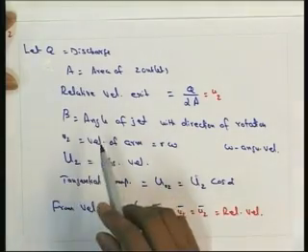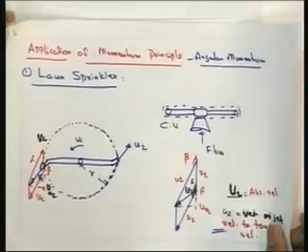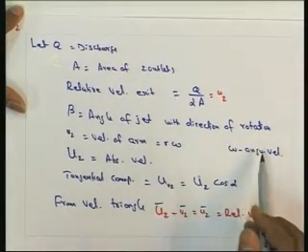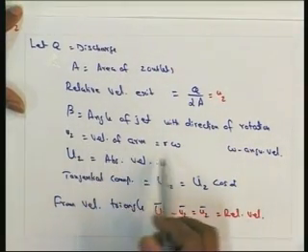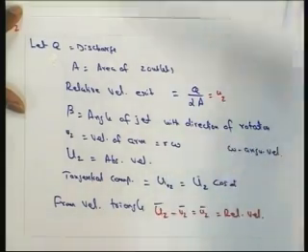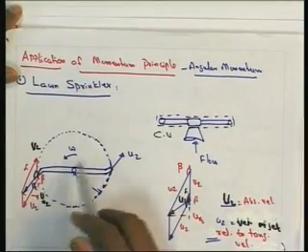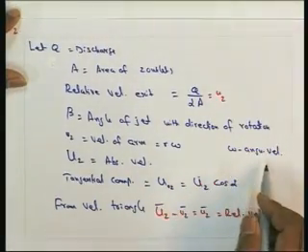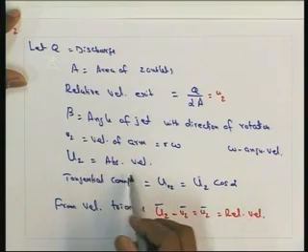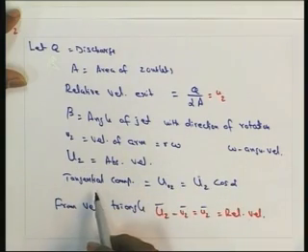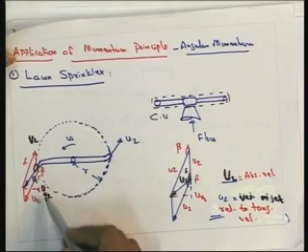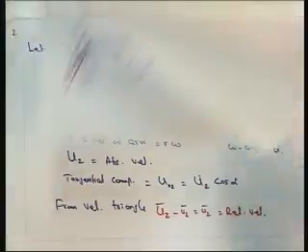So that is equal to U2, and with respect to this figure, this beta is the angle of the jet with the direction of rotation, and V2 is the velocity of the arm, which we can put as R into omega, where R is this distance and omega is the rotation speed of the arm. So V2 is equal to R omega, where omega is the angular velocity, and U2 is the absolute velocity, as we have seen, and then its tangential component. So here you can see that if this is say U2, then its tangential component you can just draw.